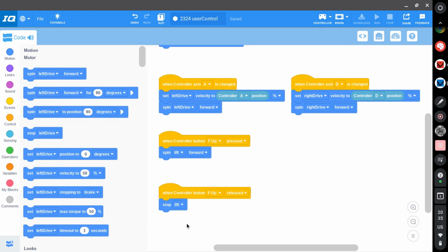But you'll notice that we don't have any velocity. By default, these motors run at 50% speed, but let's say we don't want it to run at 50% speed. Let's say we want it to run at 80. We have to change the motor name as well. Never run it above 95. Don't do it. You'll burn out your motor. It's over. Resources are limited. Motors are expensive. Don't break the motor, so don't run it over 95 is my suggestion to keep your motor safe.